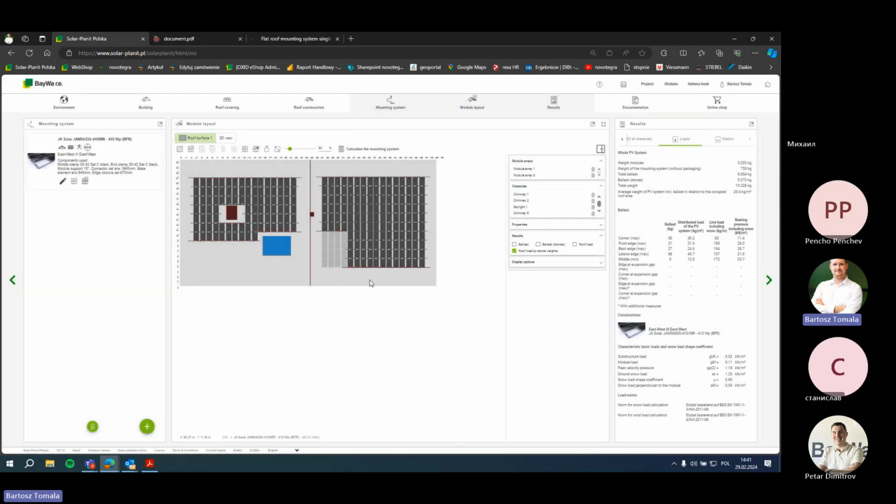We are not making larger inclinations, because a larger inclination will require more ballast. For example, between 15 and 13 degrees, it doesn't change the yearly production so much. It's a difference of maybe about 1% of the production, and you will be required to put much more ballast.